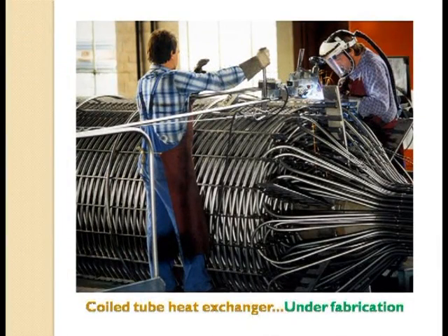Now you see, this is another heat exchanger called a coil tube heat exchanger. There are a large number of tubes. Through the tubes you can pass a large amount of fluid. Construction-wise, you have fluid tubes for carrying one or more types of fluids, but the entire tube bunch will be placed inside an outer casing. The space between these tubes and the outer casing, and inside the tubes, has lots of empty spaces. Through those empty spaces you pass another fluid with which heat transfer has to take place. So heat transfer will be between that fluid passing through the empty spaces and the tube.